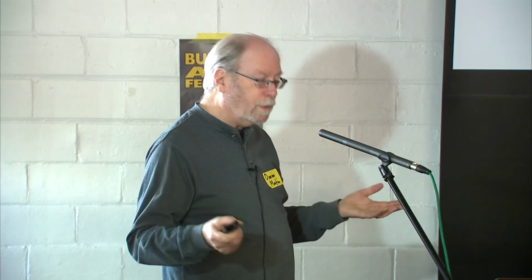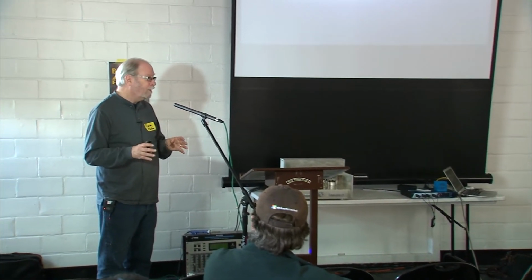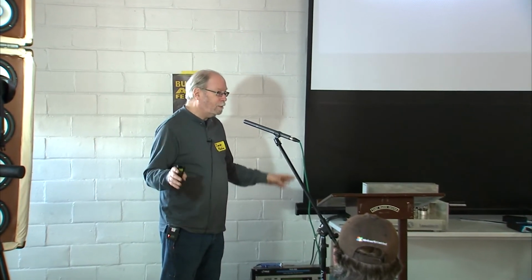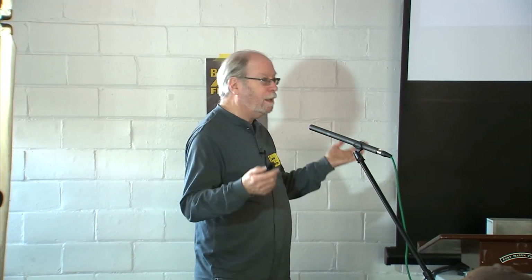And for the industry, it's perfectly fine. So you can't really expect the sound interface on a desktop or a laptop from the last 5 to 10 years to be particularly good. And clocking is an issue with those. They're not designed as high-performance instruments. You don't get a nice PLL in there to adjust your clock. So you can have a lot of errors on the capture side just because of jitter and things like that. I've actually run into sound cards in full-fledged computers where the 44.1 was 44. It was that far off, way out of spec. But, you know, they derived that clock from something else and it was lots easier than making it right.